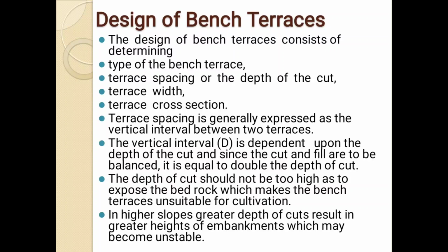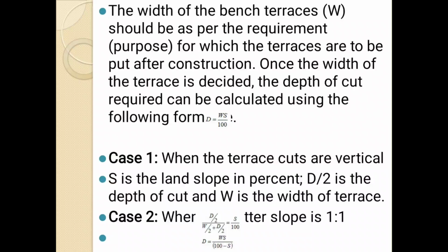Next, the depth of the cut should not be too high as to expose the bedrock, which makes the bench terrace unsuitable for cultivation. In higher slopes, a greater depth of cut results in greater heights of embankment, which may become unstable. The width of the bench terracing, W, should be as per the requirement for which the terraces are to be put after construction. Once the width of the terrace is decided, the depth of the cut required can be calculated using the formula D = WS/100.